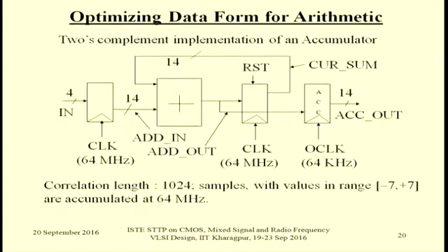Now, this 1024 we have taken artificially, 1024 means 2 to the power 10. Okay, now if you add two numbers, definitely there is an overflow of 1 bit. Now 1024 means 2 to the power 10 order of magnitude. So if all the values are very large, there should be a scope for 10 bits for containing the overflow.